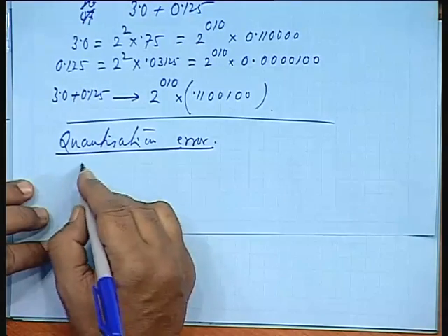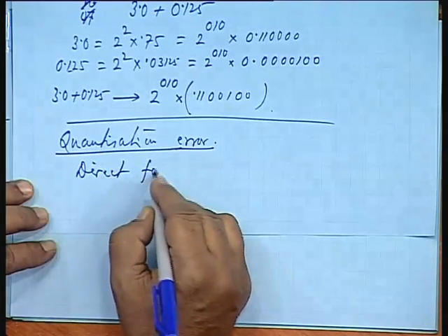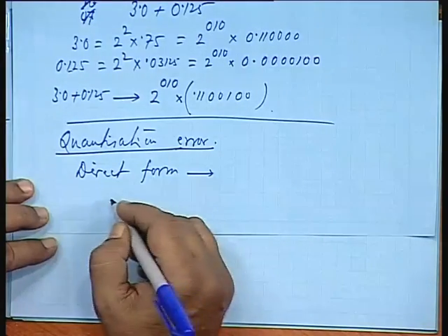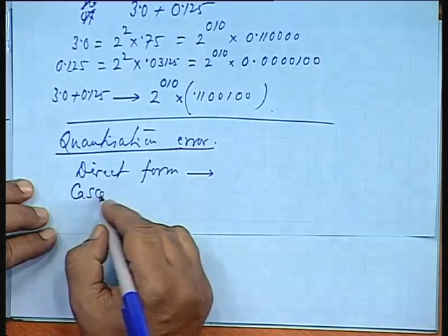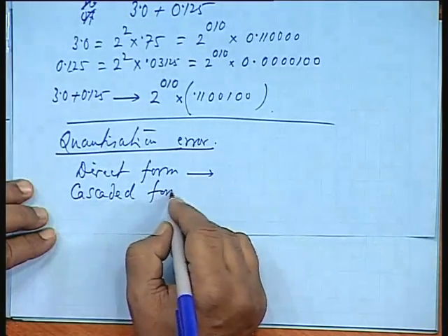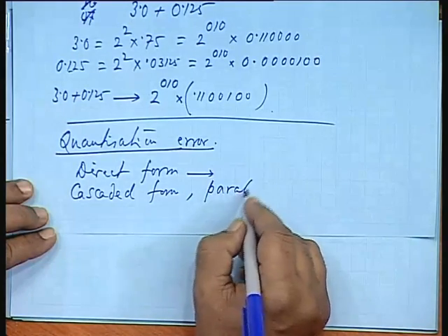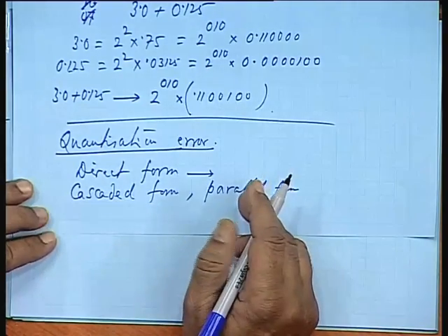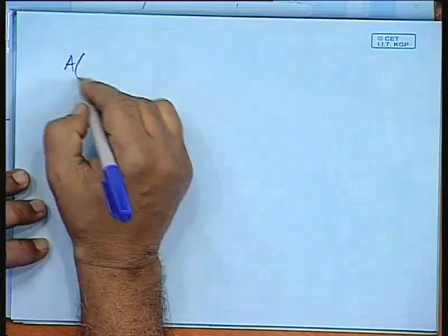In the direct form, the coefficients of the polynomials will be appearing in the structure as constants, as multipliers, is it not? In the other forms, that is, if you have cascaded form or parallel form, the constants of these are not going to affect all the roots, they are going to affect only that particular pair.